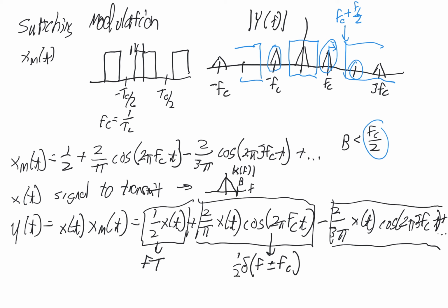Now, what that gives us is exactly our modulation. Our modulation property says we don't need the original signal. We don't need these things at higher frequencies like plus or minus 3fc, but we do want one at fc, this higher frequency, to transmit it on.